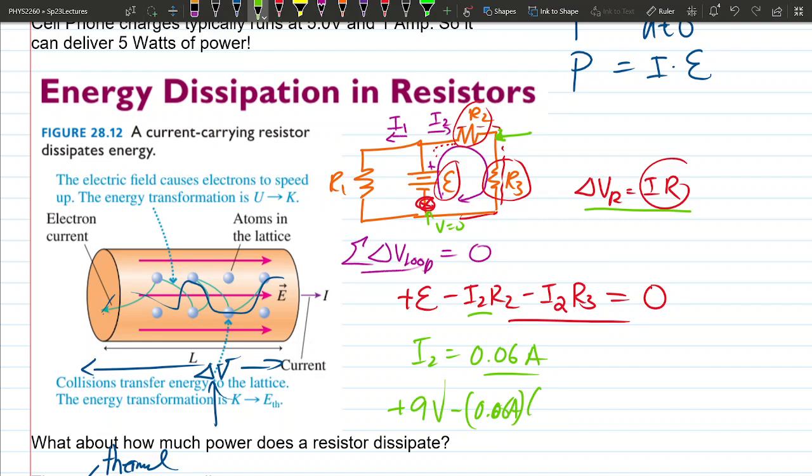amp, and then R2, you guys remember what R2 was? Was that the 50 ohm, I think? Yeah, that's the 50 ohm. Okay. And now you are actually at this point, and you can calculate the voltage at that point. This is the voltage between the 50 and 100 ohm. A lot of times you just call it point A, and then say the voltage at point A, VA or something like that. If you calculate this, you should get 6 volts out of this, okay?